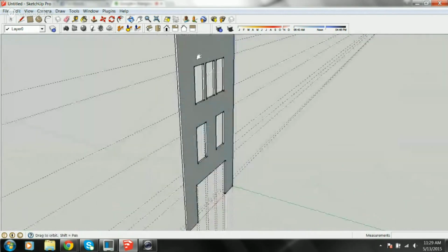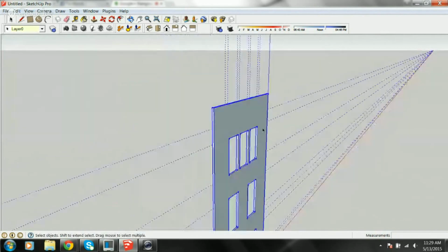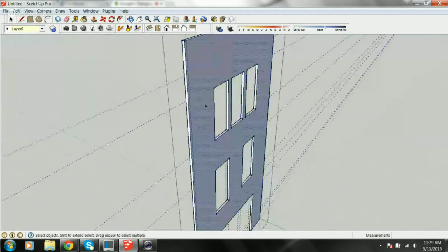This is one of those things that came up in Ed's video about surfaces. Like if I just click on it once, I'm going to get the whole object. Okay, it's not an individual face. I got to double click it to get inside. If it was ungrouped, it would just pick that back side of the wall as a plane. Exactly, just like I've done within the group here.